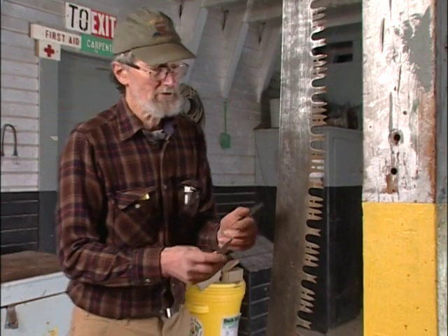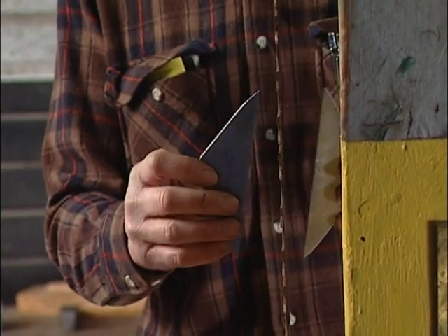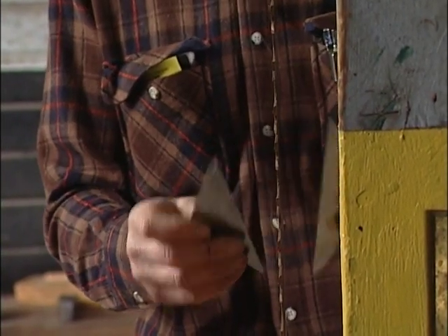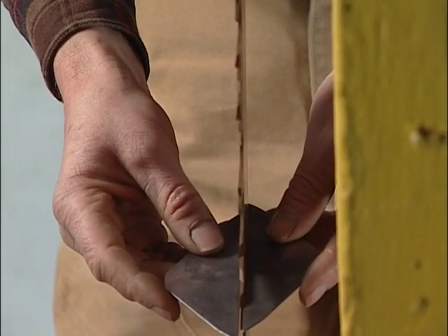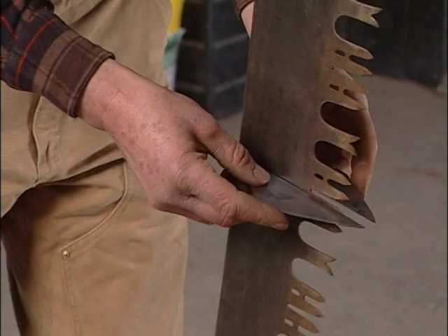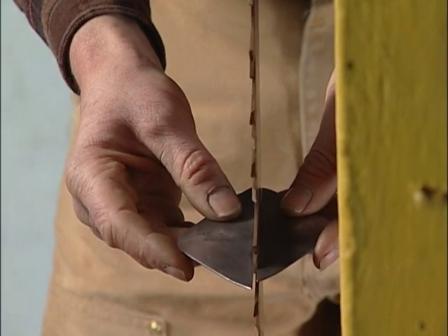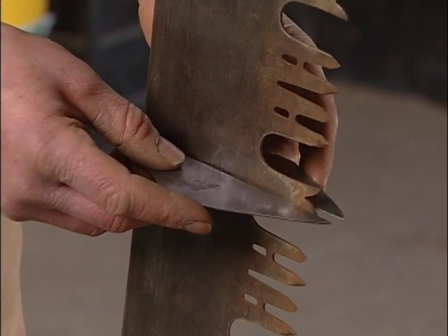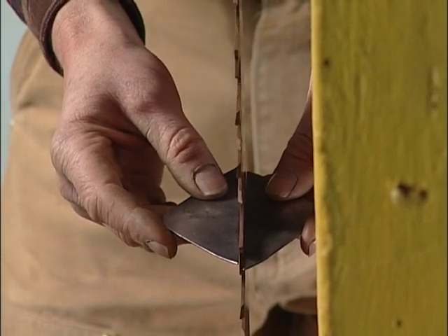I'll use a pair of short straight edges. These are just 6-inchers, and instead of using them vertically on the saw or along the axis of the saw, I'll do it across the saw like this, with the straight edges extending beyond the tips of the teeth. If I have a raker that's bent, it will hit one or the other of the straight edges. Normally, a raker will never touch a straight edge in a situation like this.